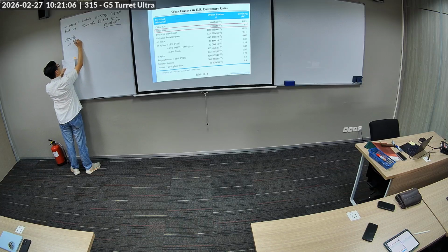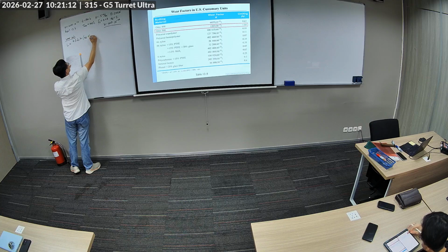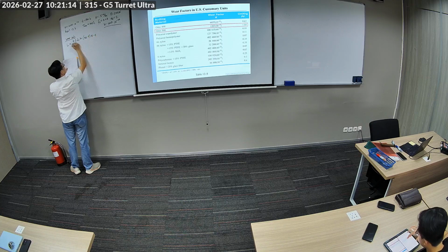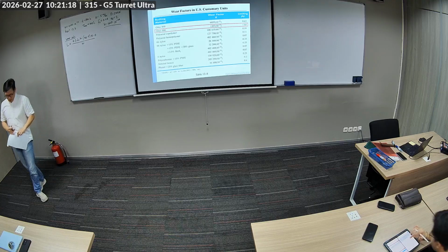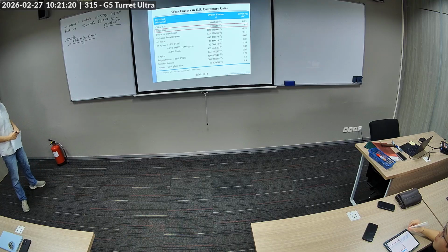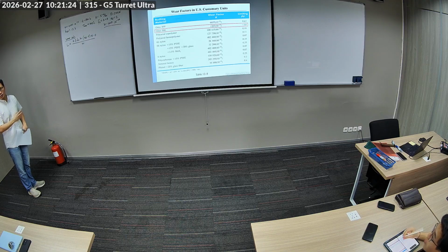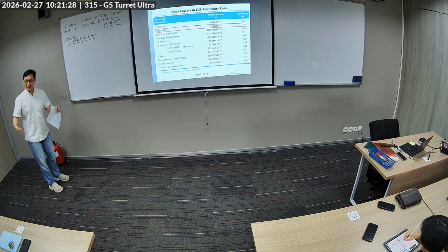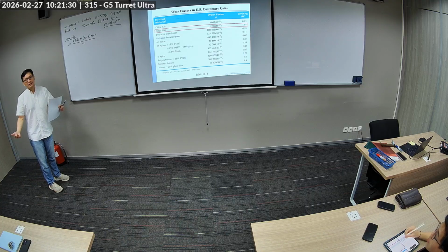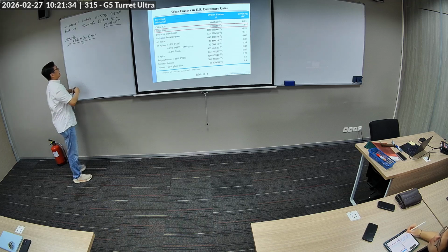Because we're selecting size, right? I'm interested in solving for size. So if I rearrange my wear equation and put L on the left-hand side, this is what I get. And L is the length, right? We are selecting bushing size. So I'm interested in length, given all this.